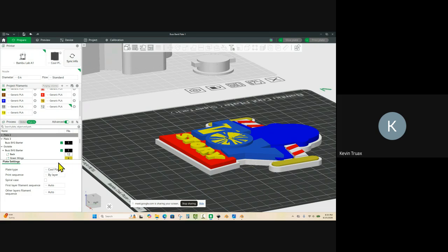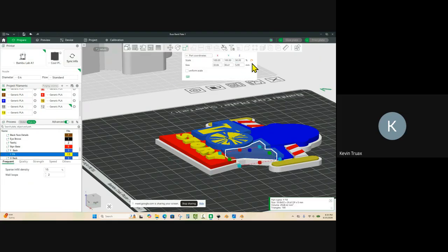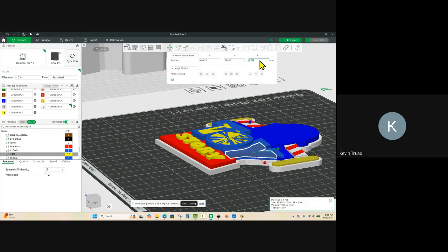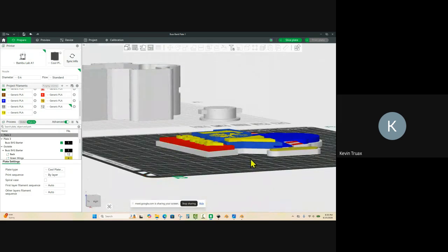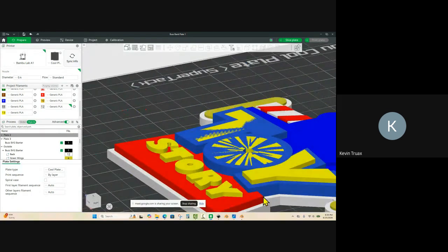The fill for Y, so let's come over here. So where is our Y fill? There's our Y fill, 2. We'll make that 2 millimeters thick, and it's going to sit on top of blue. And we know blue is sitting at 9 now, right? Because it's 5 and 4, 9. So this is going to be 10 on the Z. So now you can kind of see how this is all going to come together.